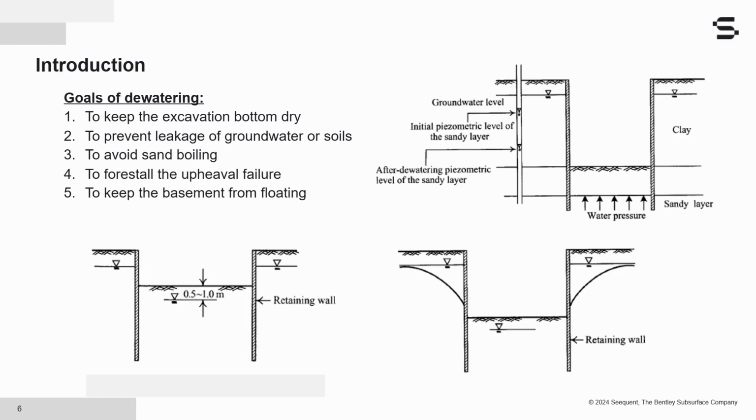Usually, when we have an excavation in less permeable soils like clay, there is no need to lower the groundwater level to that elevation, as the groundwater flow is so slow in clay soils that flowing of groundwater into the excavation zone will most likely not occur.